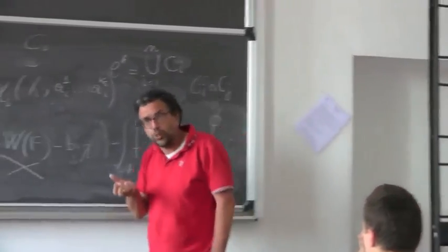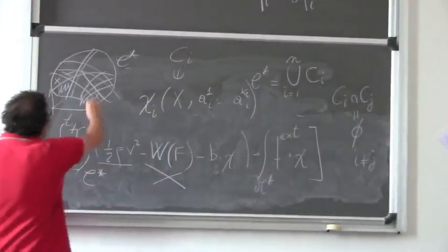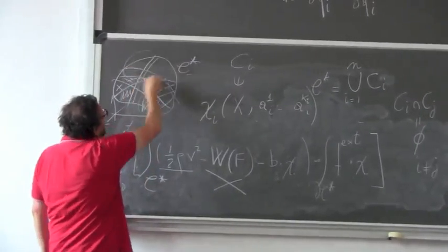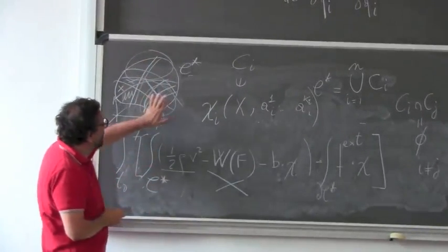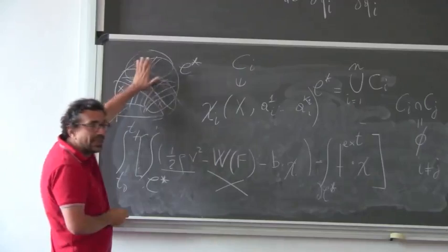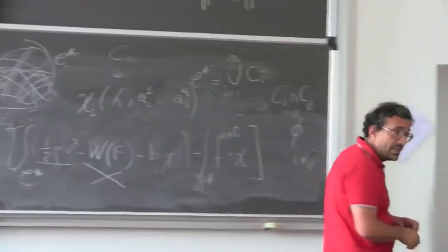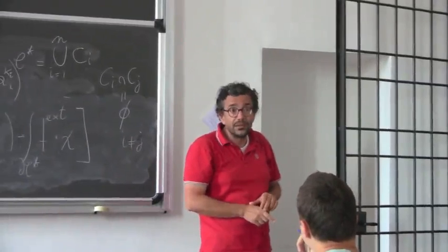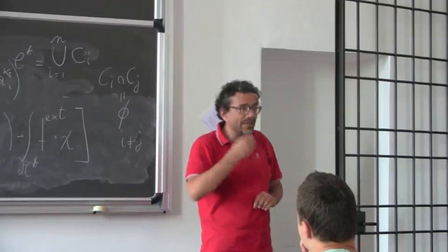Okay? But it is not true, because when you need to study problems and you know that here something strange is happening, while you are rather sure that here nothing strange is happening, you could decide that your finite elements here are full of parameters and your finite elements here have a lower number of parameters, and this could make your numerical simulation quicker, because you are not wasting your time in these useless calculations.